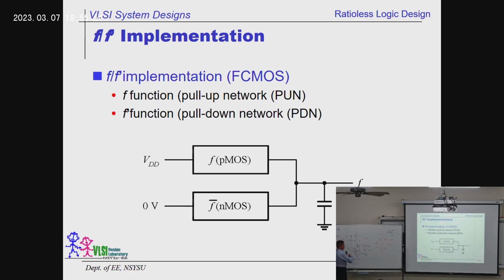So we like to cut it in half, and then we're going to have the single R, just like the one we had before. How do we reduce the impedance? According to Ohm's law, all we need to do is increase the size. When the size of the transistor increases by double, the impedance goes down by half. So basically, what you should do is increase the size. Because we double it, it equals 4 times the original width.